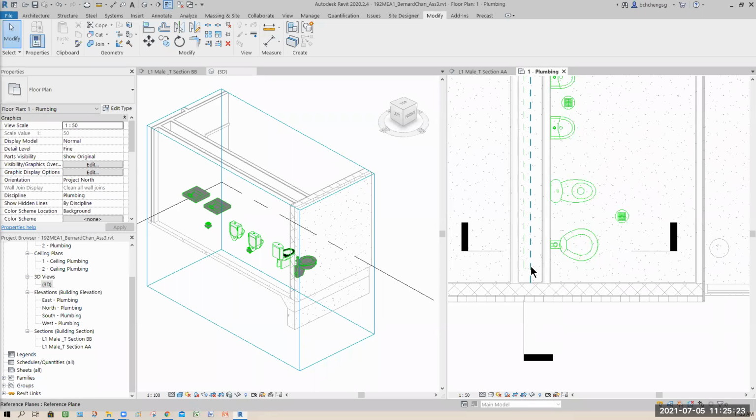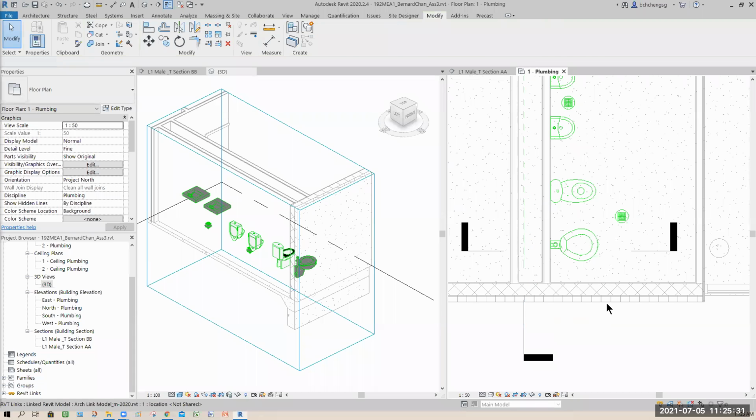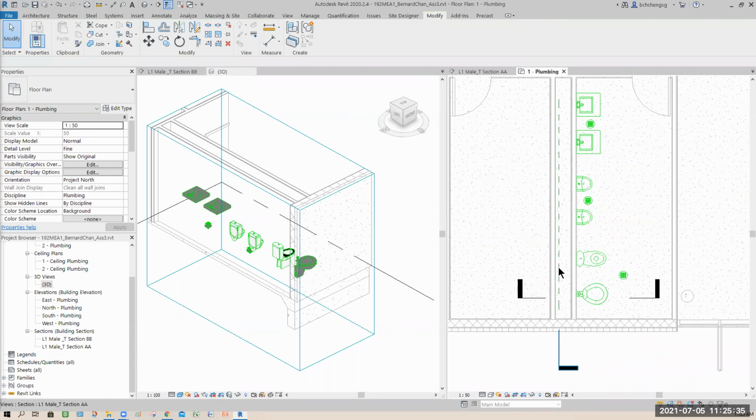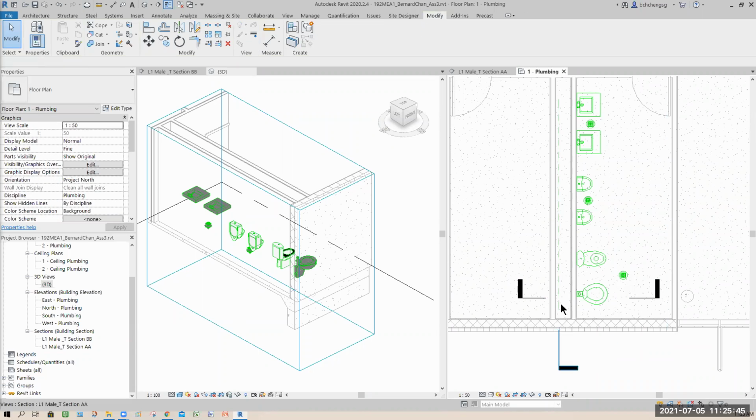All these I leave open to you all, so you guys just adjust accordingly. So if I base on this, the center is not important anymore. It's based on this. Okay, delete away like that. Yep. So this is my male. So for those doing the female side, you guys take note. Okay, grid line. You can't select the reference plane, use the tab key, remember.